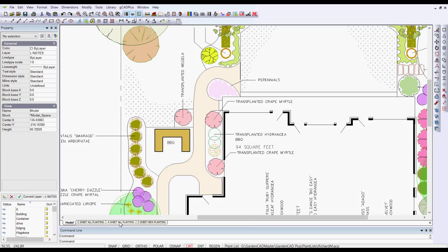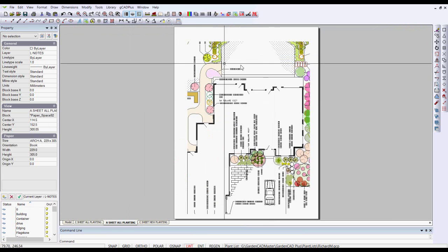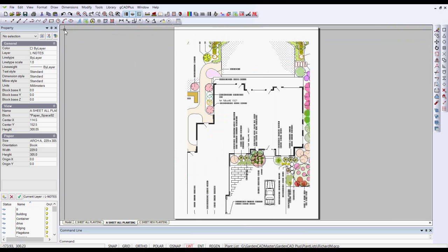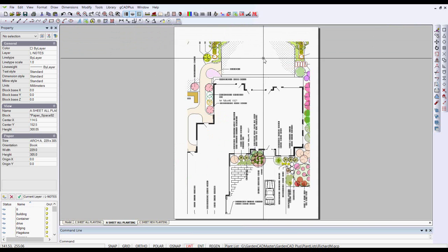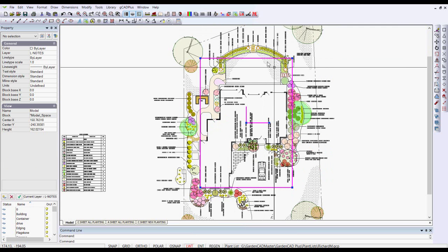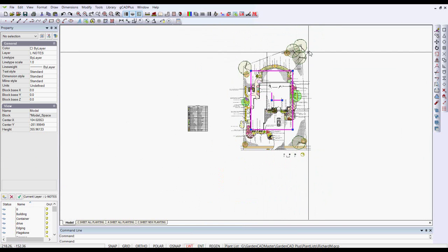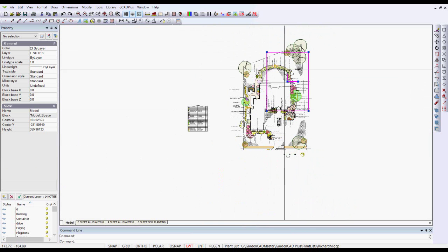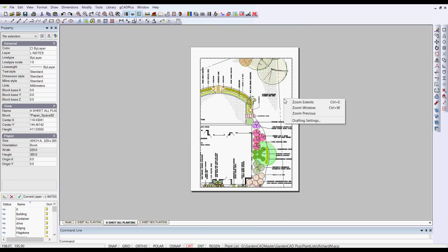But what I'm going to do is move to an A size sheet. I'll zoom extents. Now I'm going to go, whoops, we better dive into the A size sheet, and we need to set the box around the whole drawing. And what's happened here is I've got a fixed scale. So I'm going to display on the line weight.